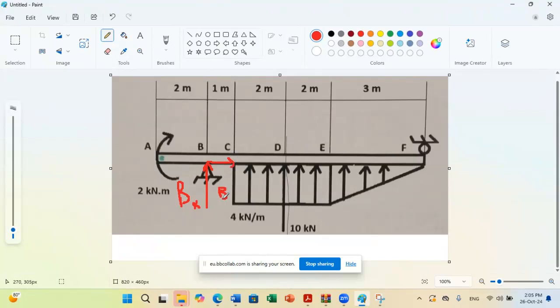And I have a roller at F. If you look at the roller here, this is Y and this is X. The roller is on the upper part, so the contact line is here. So how will the force Fy be? Downward. Fy will be downward. Great. Okay.